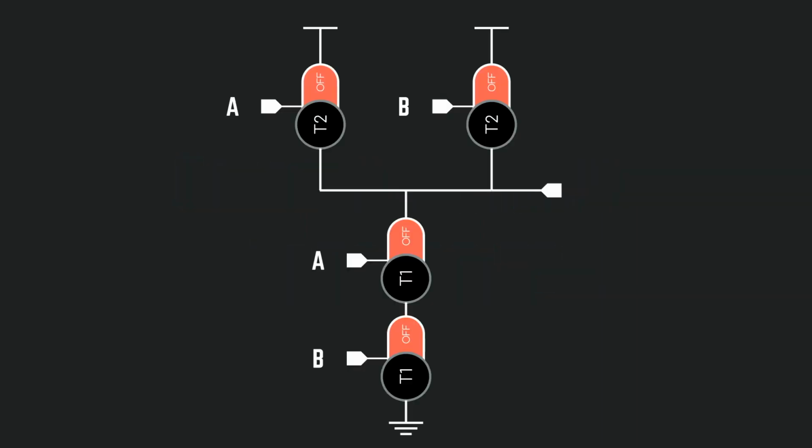For example, consider this circuit. There are two inputs, named A and B, coming from a previous stage in the circuit. The input values are 0 or 1, or 0 volts or 1.8 volts if we wanted to remove the 0 and 1 abstraction. The top section of the circuit contains switches from the second category, where the switch turns on when a 0 is applied and passes a good logic 1. Since these switches are good at passing a logic 1, we connect a logic 1 to one side of the transistor, where logic 1s will be designated by the color green.